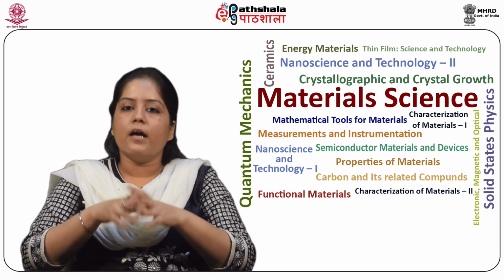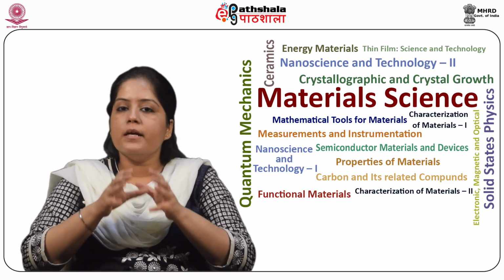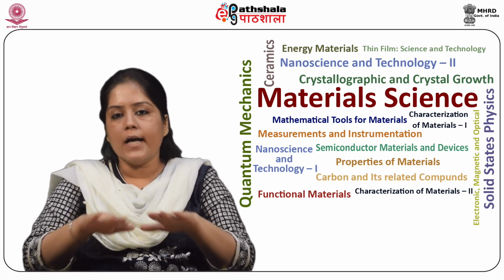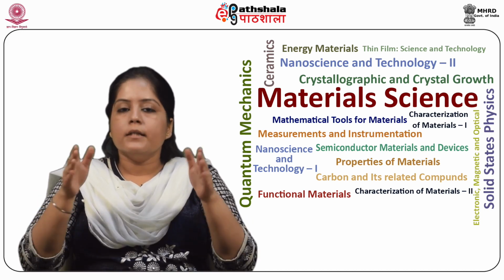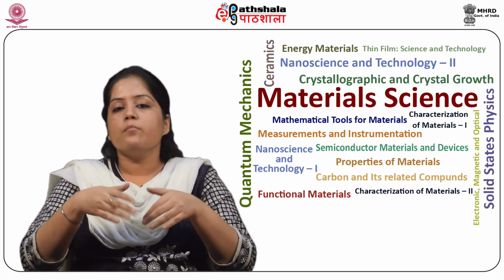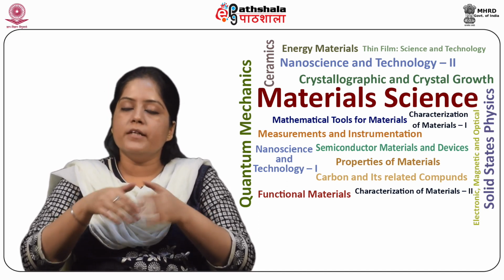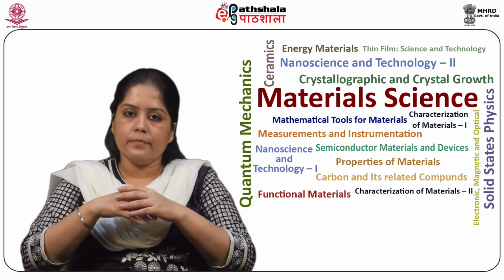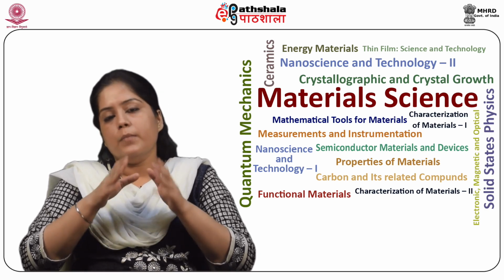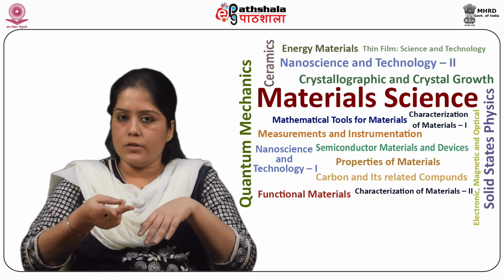Piezoelectric sensors are very rugged in nature. That is, they have an extremely high natural frequency and an excellent linearity over a wide amplitude range. They have a very high DC output impedance, which can be modeled as a proportional voltage source and filter network. The most common physical quantities that are measured by piezoelectric sensors are pressure and acceleration.